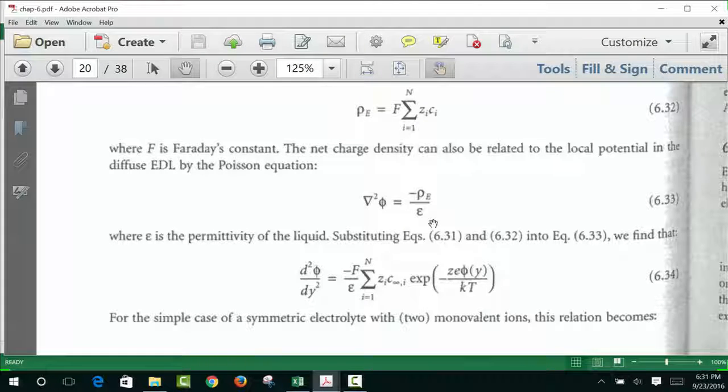It's like if I give you the specific gravity. Remember what is the specific gravity of a liquid? If I tell you specific gravity of the liquid is 0.8, give me the density. What do you do? You multiply the specific gravity times the density of the water at 4 degrees C, which is 1,000. So same thing, if I give you the relative permittivity and tell you, well, calculate the permittivity of this fluid, you multiply epsilon R by epsilon naught. The relative permittivity multiplied by permittivity of the vacuum, you get the total or the absolute permittivity. All right?